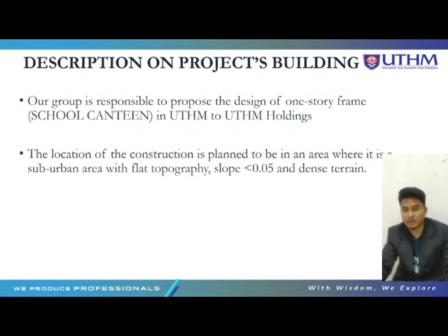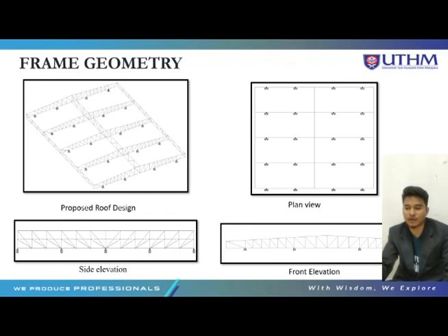Decision on project building. Our group is responsible for proposing the design of a one-story frame, which is a school canteen in UTHM. The location of the construction is planned to be in a suburban area with flat topography, with slope less than 0.05, and dense terrain.